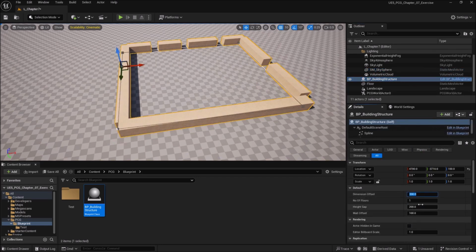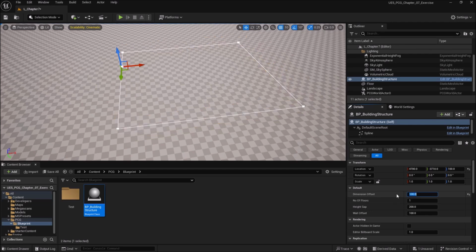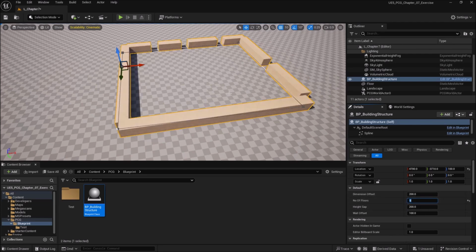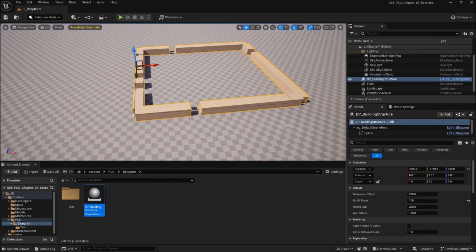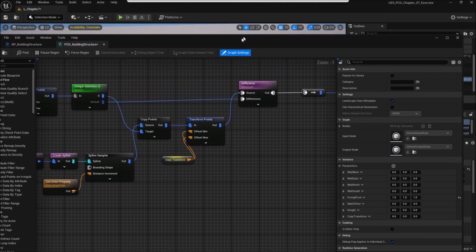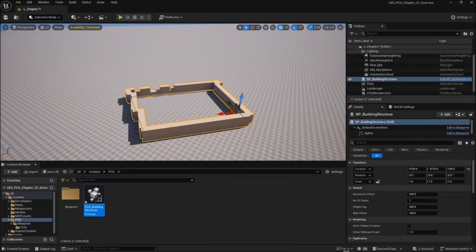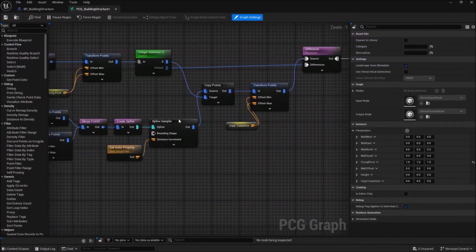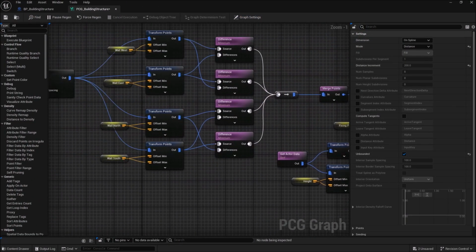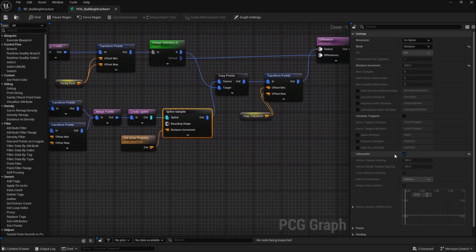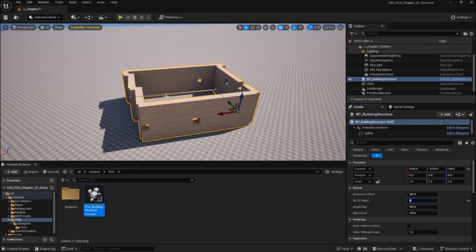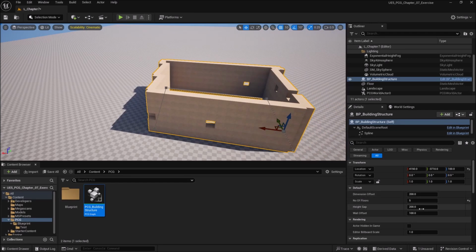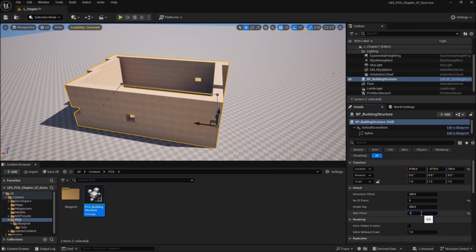Make sure your walls also, because the moment the height might not work, so in this case, you always keep in mind that on every spline sampler you work with, always set this to unbound. And that's why things didn't work at the beginning. So just compile this. Now you should be getting some really cool results. And you're still getting the corners issue, but this is very fixable. So you can just basically set this to 0 in this case, and the problem will be fixed.